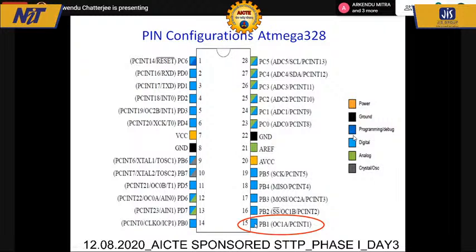We need to drive this signal out from the microcontroller. And who decides this output and input? It is the DDR register. So at first, we will configure the DDR register so that this port B1 or PB1 is an output. Then by filling the values of the timer control registers and the PWM control registers, automatically it will operate as OC1A. So the output will be PWM.